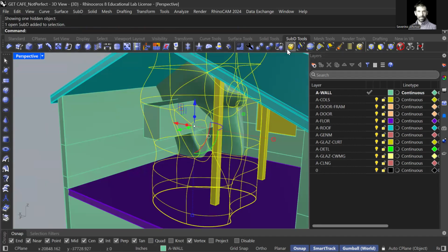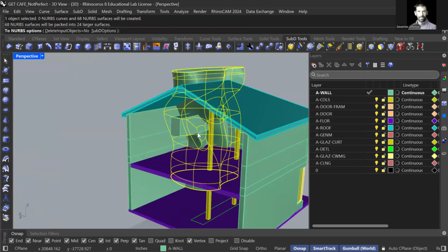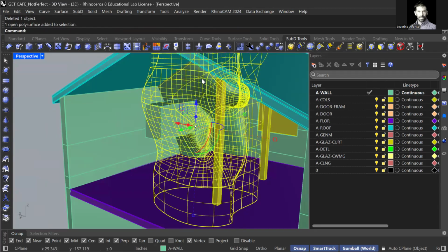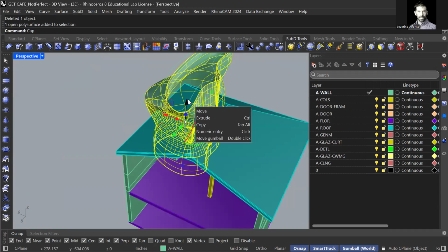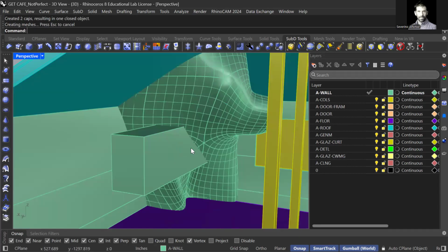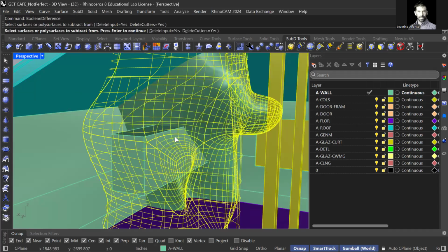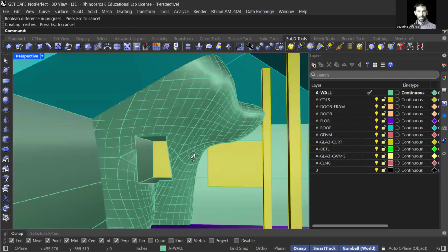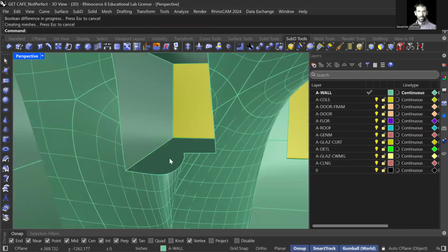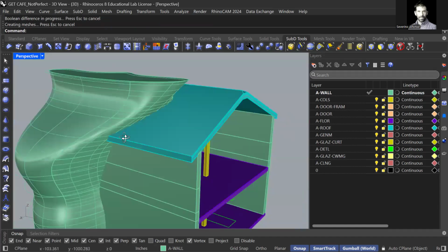Show. I'm going to turn this now into NURBS. So that turns it into a NURB. So I can maybe now set these. This one, I can cap the bottom. So that's actually a solid. I can do some kind of weird thing, such as a Boolean difference of sorts. This one, enter this one. So it could be a weird thing there, like a platform to sit or just a surface to stand on.